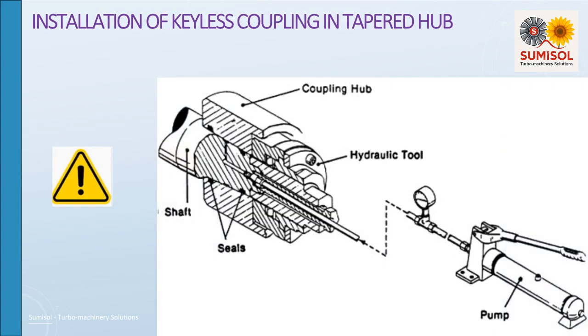Exercise safety step 3. Expand the hub. Pump the high-pressure pump. As the pressure increases, the hub will tend to move off the shaft. Prevent this movement by occasionally increasing the pressure at the installation tool. Check for oil leaks. The hub should not be advanced on the shaft if leaks exist. If the pressure drops, remove the hub and replace the O-rings.